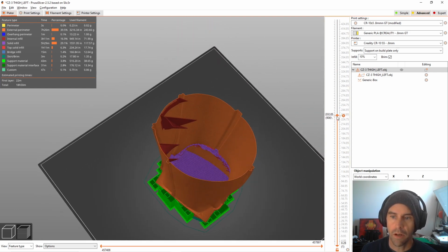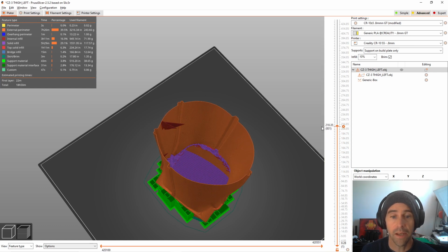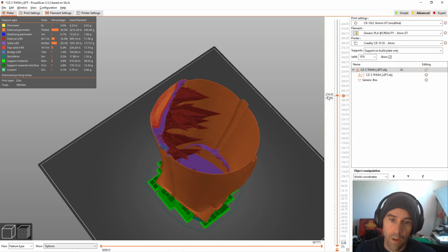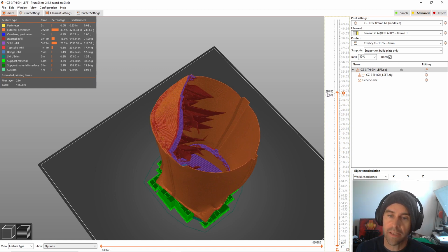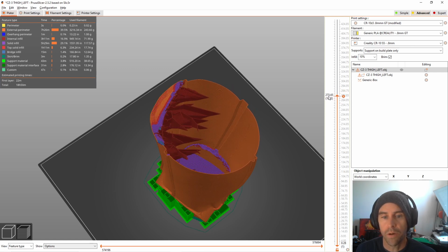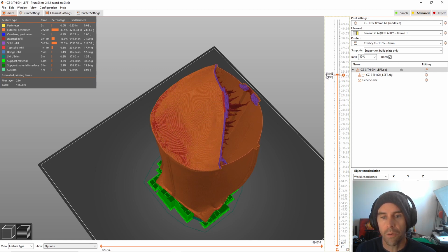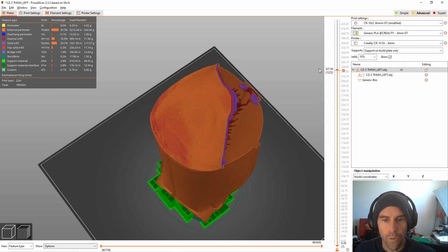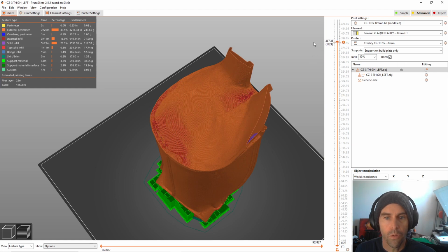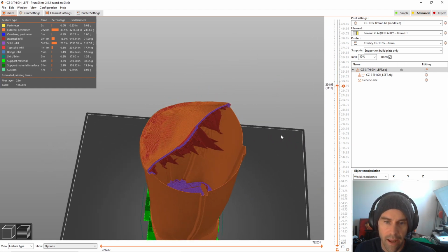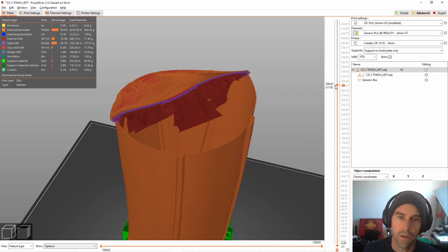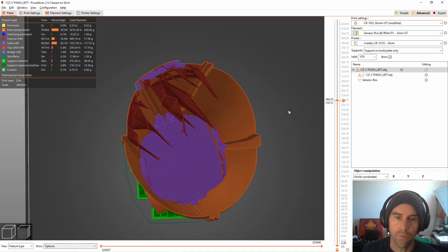See, it just starts coming off of the wall. So the whole print's hollow real fast, and then right here it starts adding these little things. With the method that it's using, it slows down a lot as the printer makes these weird little pieces. But you see how that grows like that? That's pretty cool. So if you need to have some support, but you want to remove it in the end, this is a way to do it. Again, it adds a lot of time, but you can tell it's using very little material to do that support. It's really cool, right?